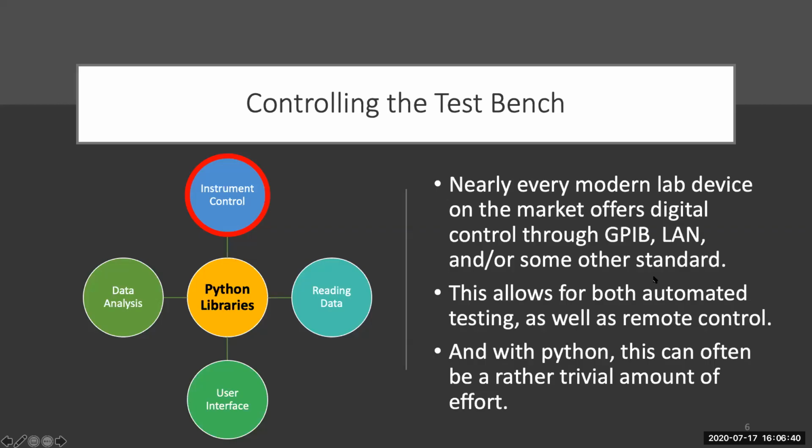All right, I begin our discussion with the topic of instrument control. So all of our devices, as well as most commercial devices on the market, offer some kind of digital communication through TCP, GPIB, or some other common standard. And there are a number of use cases for this. Some of those I mentioned before, but maybe a more serious use of this would be to automate your testing.